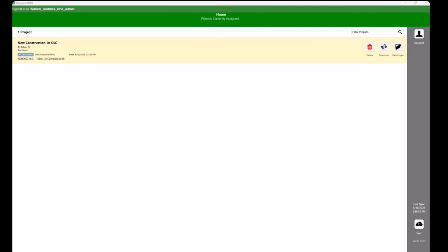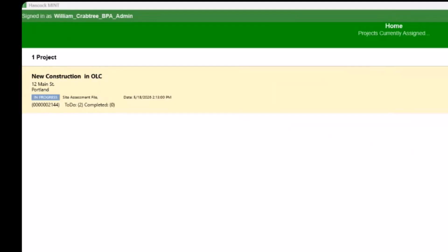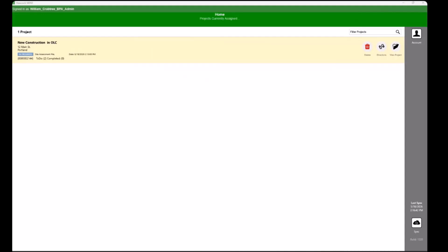This video will start with a project that has already been synced to Mint. If you are unsure of the process for starting a project in the Hancock Cloud portion of the OLC, please review parts 1 and 2 of this series entitled Creating and Submitting a Retrofit Lighting Project. These steps are the same for both retrofit and new construction projects. Lighting code information, allowances in watts per square foot, can be obtained via local authorities or the use of ComCheck, a free online tool. Trade Allies contractors can provide details on the installed or proposed lighting equipment.